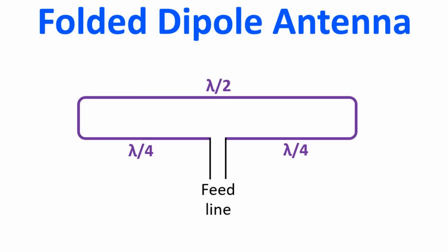Characteristic impedance of the antenna should match that of the transmission line and radio. Otherwise, matching systems are needed for good radiation of signals. A half-wave dipole antenna has an impedance of around 70 ohms, while the folded dipole antenna has an impedance of around 280 ohms. Thus, different types of antennas have different impedance. In Yagi-Uda antenna, adding parasitic elements changes the impedance of the antenna.